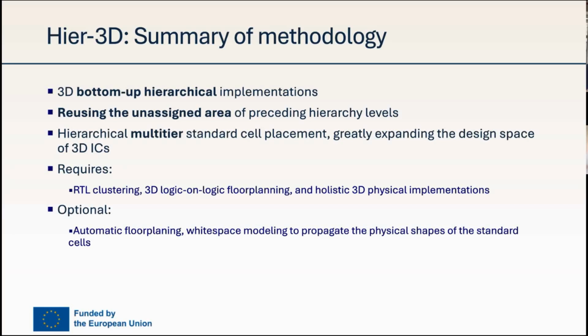In order to enhance the methodology, it is also possible to add one automatic floor planning step, and also it's possible to add some improvement in terms of the definition of what is white space, so that we can get a trade-off between the possibilities of recovering the space that we have in different iterations without having to create a much detailed LEF file.